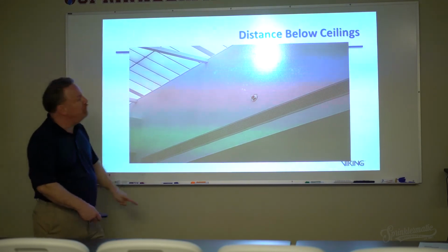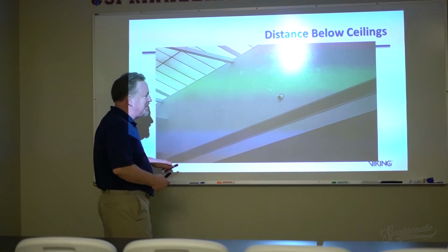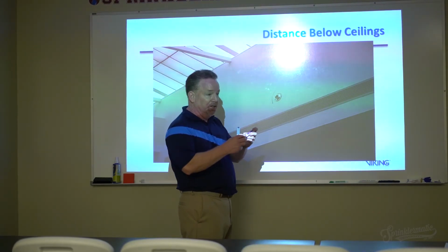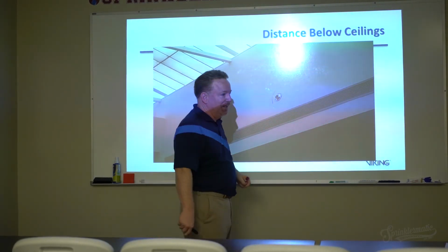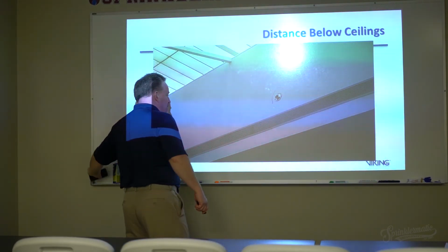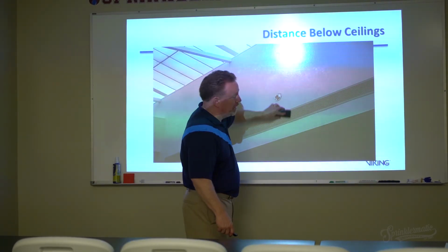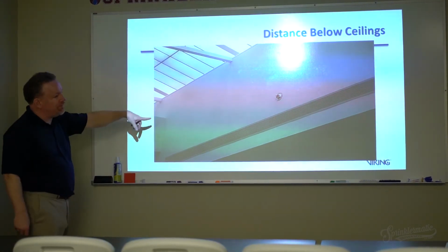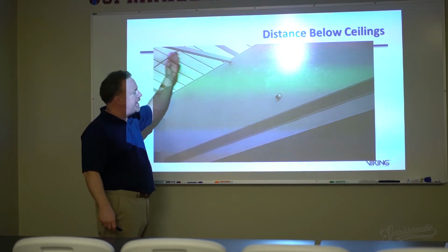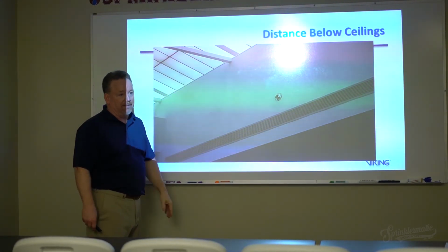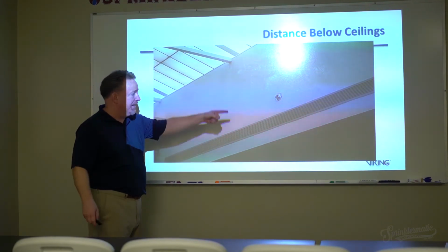Not even if we put a little nun's hood over the top of it, which I saw at Pittsburgh International Airport, to act as a capture. That's not going to work either. It's pretty creative, but it won't work. You've got to put the sprinklers up. You can't avoid putting the sprinklers up in the glass skylight area. You're not going to get it with that.